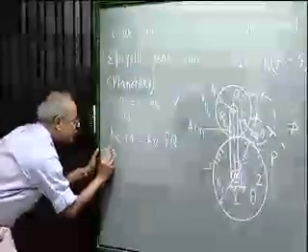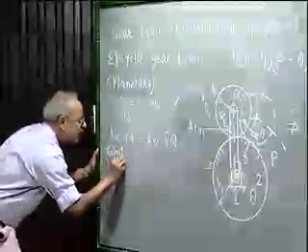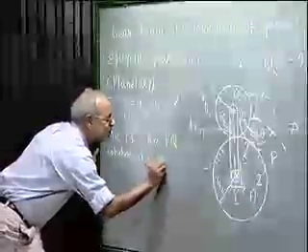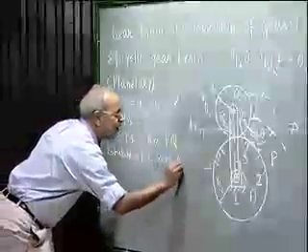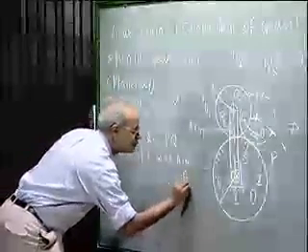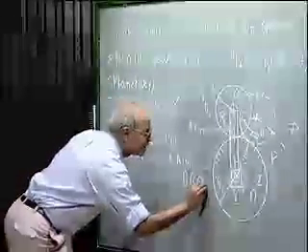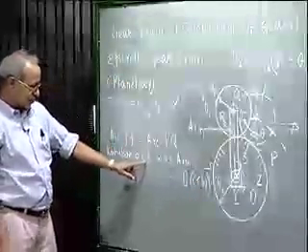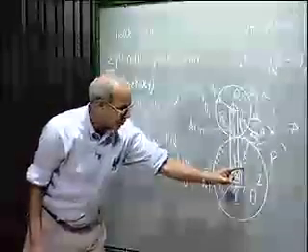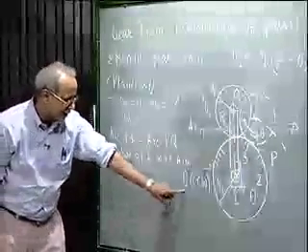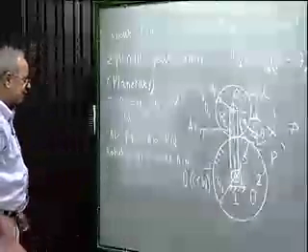So rotation of 2 with respect to arm is theta but in the counterclockwise direction. Rotation of arm with respect to 2, which was fixed, is theta in the clockwise direction. So rotation of 2 with respect to arm is the opposite of that, theta in the counterclockwise direction.